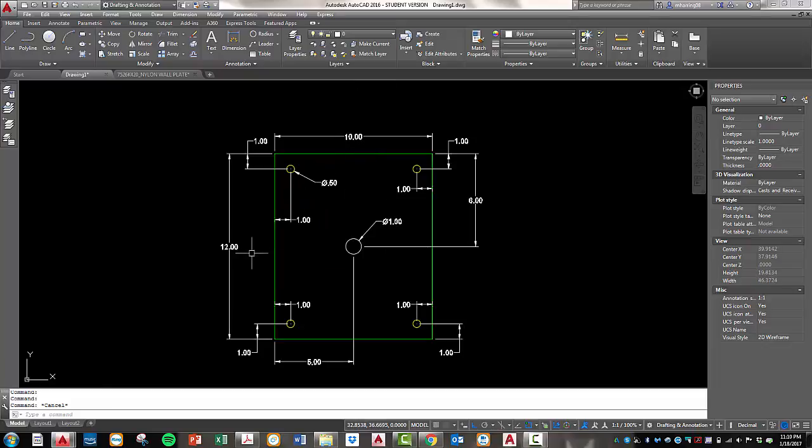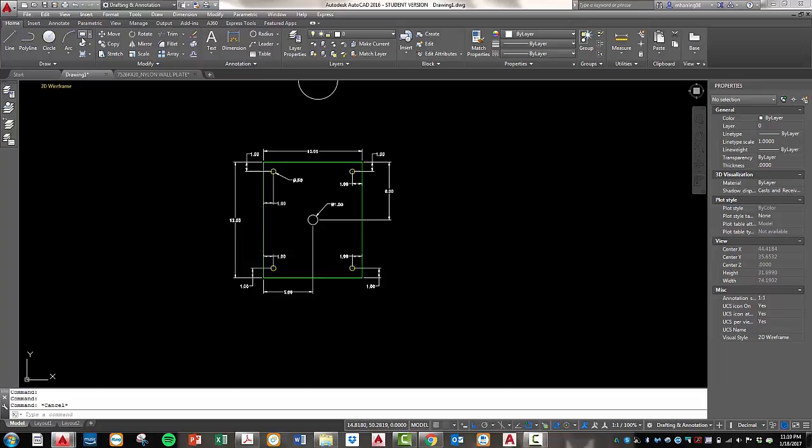Down here I have a plate that's 12 by 10. So I'll draw my rectangle. Actually, this time I'm going to do it with lines. So I'm going to pick line. I'm going to start right about here and go straight down and type 12 space. Go off to the side, 10 space. I go back up, 12 space. I come over, and as I get close, I just pick because it defaults to the endpoint, and I hit escape.